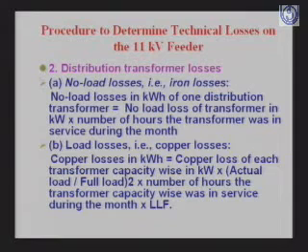Now what I said earlier, that many of the professional energy auditors don't go by these formulas. What they use is very easy for you. Please measure what is the kVAH recorded. If you have a trivector meter there, you have kilowatt hour recorded, you have kVAH recorded.